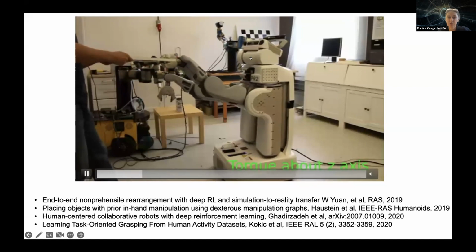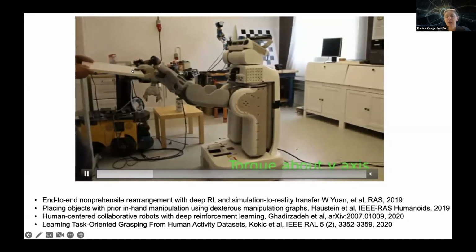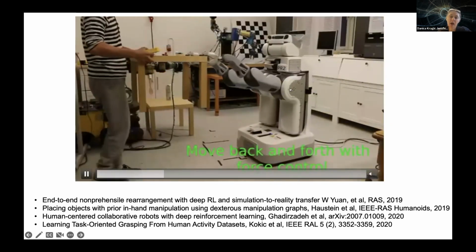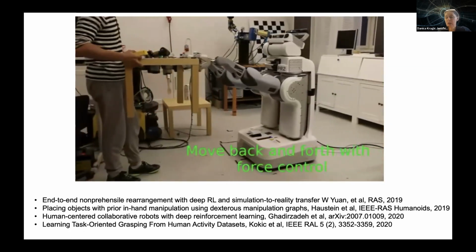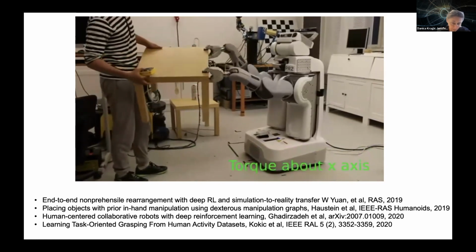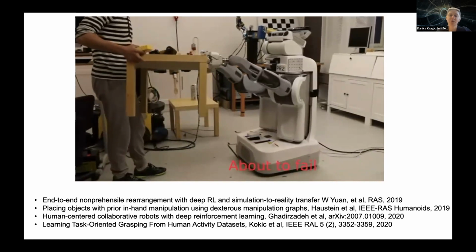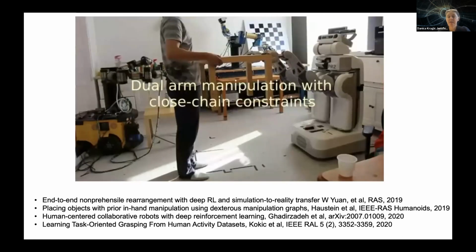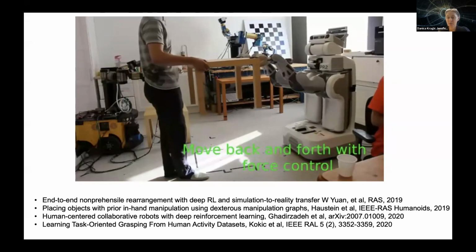Do we all use the force-torque feedback and have this kind of compliant control task solved? Does the robot or the software really understand where the joint limits are? Does it appropriately address when the robot comes to either the joint limit or whether the Jacobian works well and so on? My point is that any of these tasks that need to be done in interaction with a human need to be safe from the beginning.